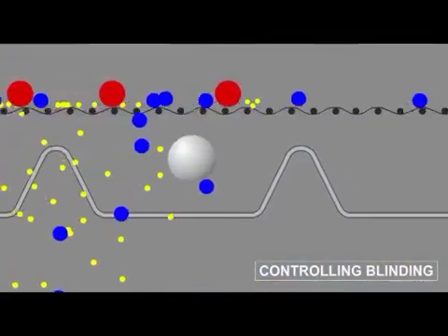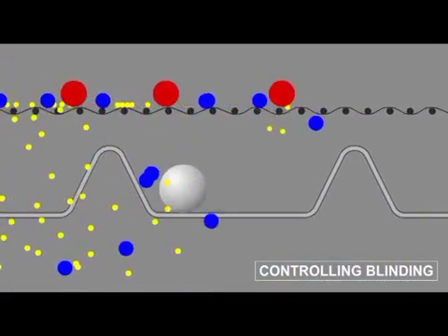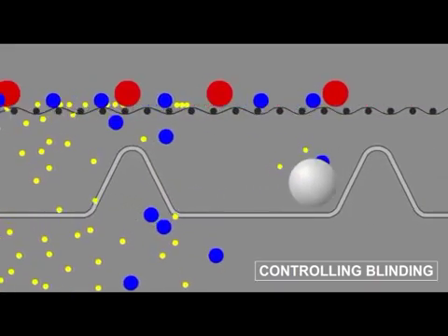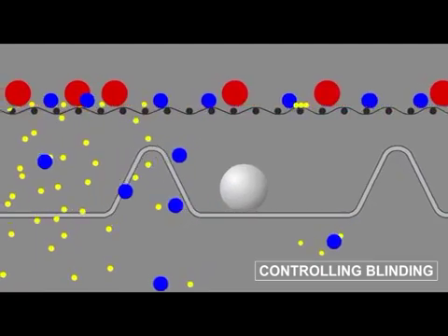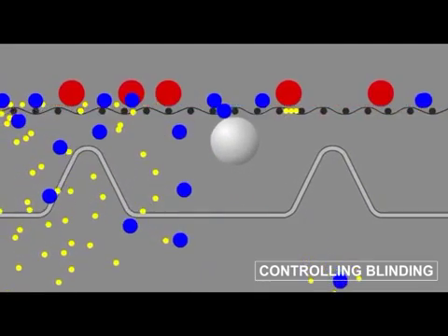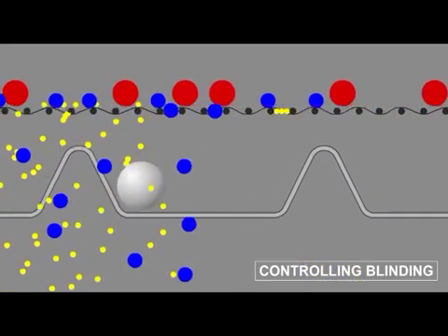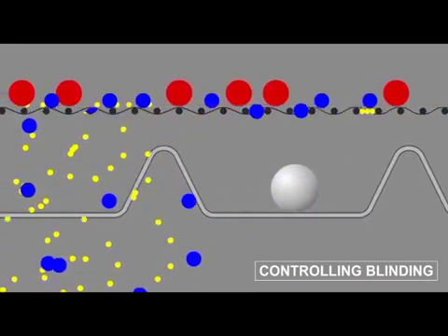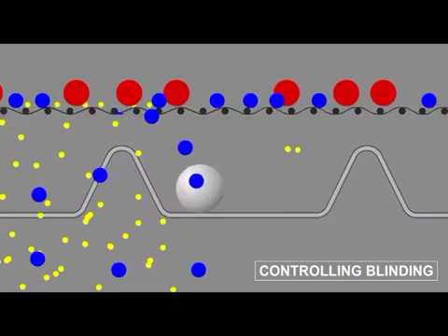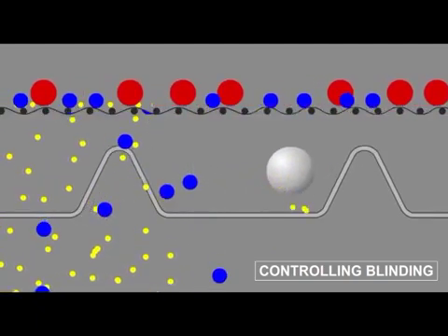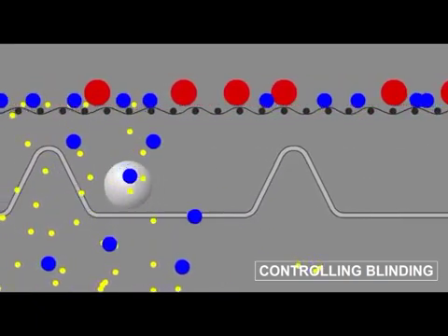The long-stroke gyratory reciprocating motion drives the mesh cleaning balls into the underside of the screen, cleaning out the material. Shorter stroke gyratory and most all vibrating screens provide less force and are therefore less effective at mesh cleaning. A long-stroke gyratory reciprocating motion will keep a screener operating longer than other mesh cleaning systems, minimizing unplanned downtime.